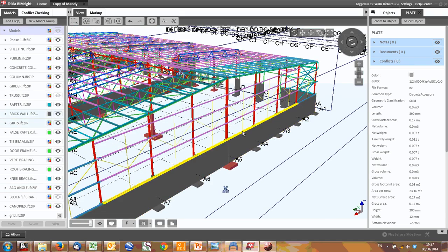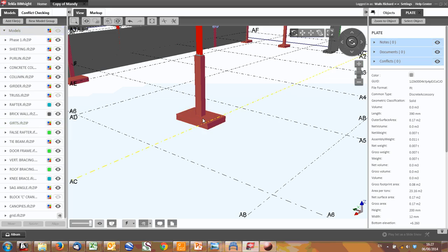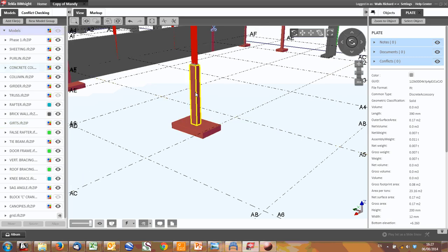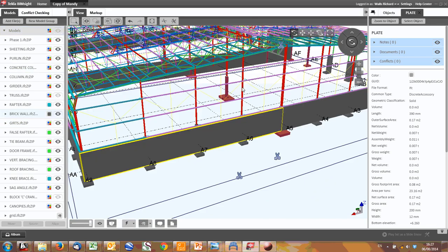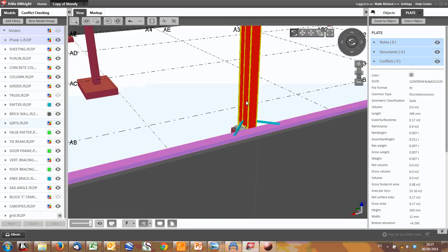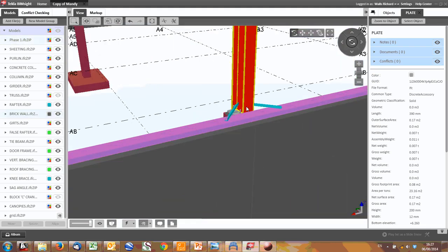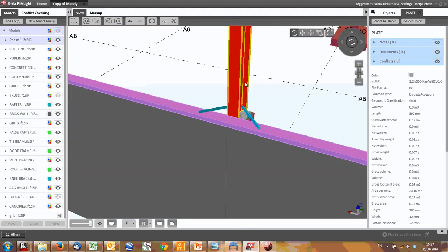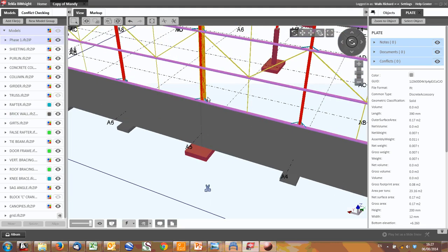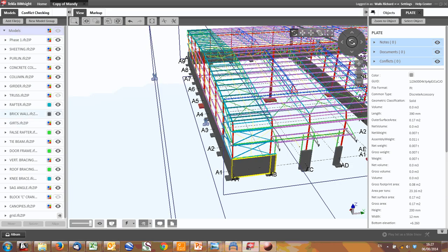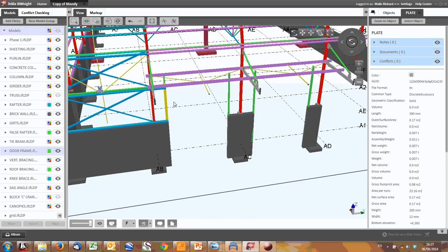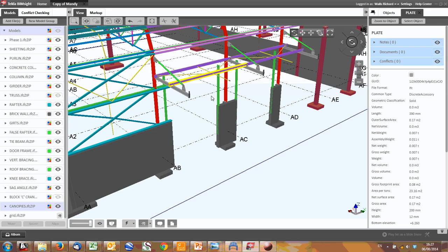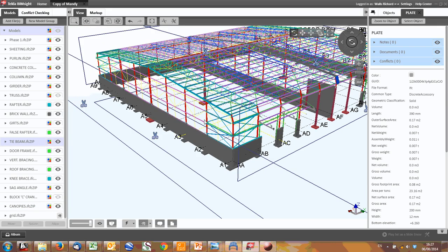Then we've got our walls all the way around outside. We've got our foundations, our bases. Our column plinths are made of concrete and support our columns. Our base plates link the concrete to the steelwork. These are knee braces that prevent the warping of the columns. And those are the main items of the structure. There are other items such as door frames, roller shutter doors, the canopies on the front. But at least that for now is the main issues.